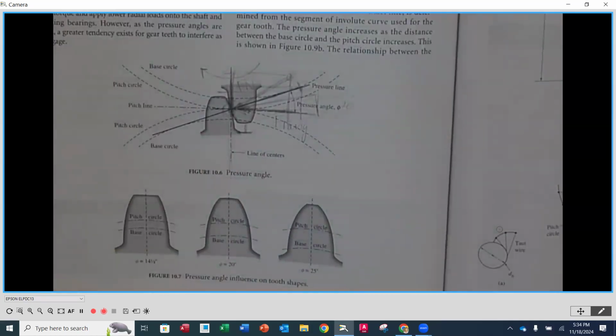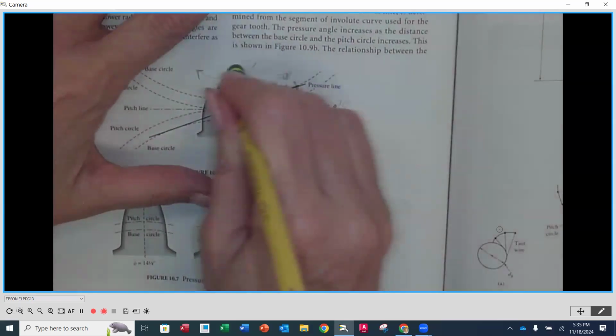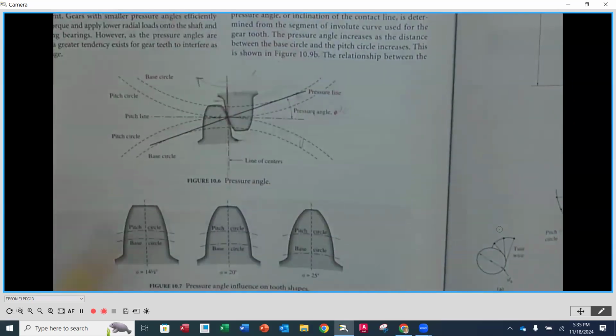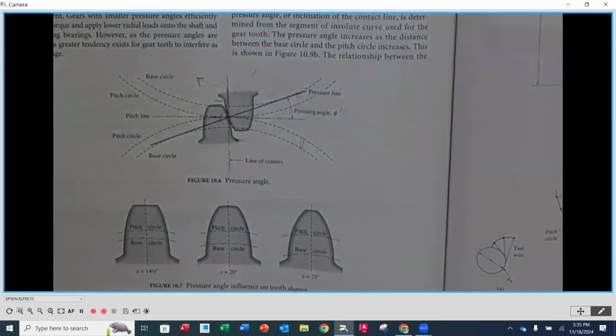We're not going to calculate any forces here, but when you get into machine design elements, you will be calculating tangential and normal forces and those pitting stresses and the bending stresses, because those are going to be the ones causing failure. So you have to size your teeth appropriately, then pick the right material, and then decide how much hardness, if it's metal, for instance, you're going to be adding to it. That's my discussion on pressure angle, and we just discussed the forces to give a visual of what's happening with the components of that resultant force coming in on the pressure angle.